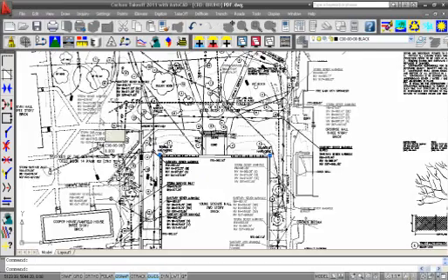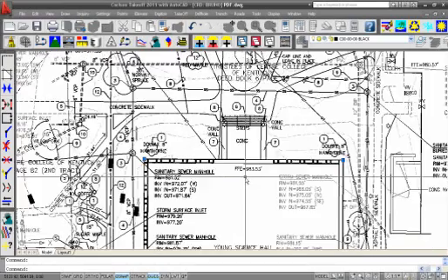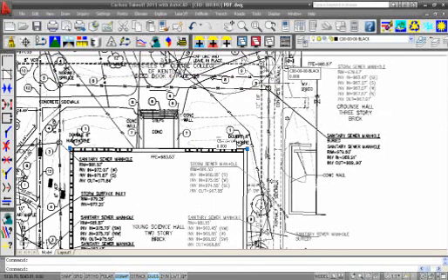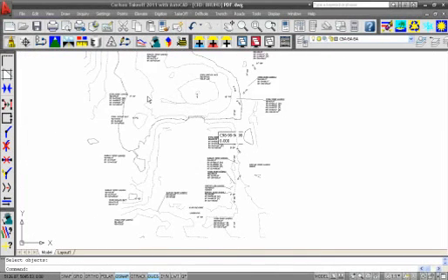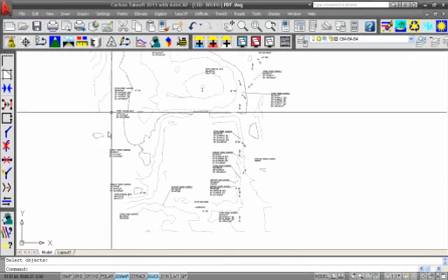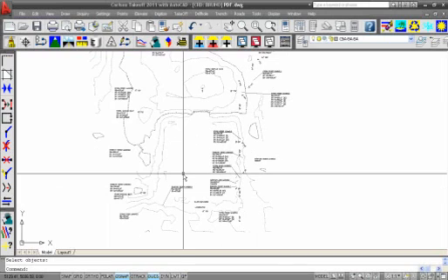Okay. Yep. As you can see, I could isolate layers. Now, if I use the little palm tree, isolate, and I click on one of these layers, okay, I can see they're parsed out as contour lines because they're a different grayscale than the rest of the line work.